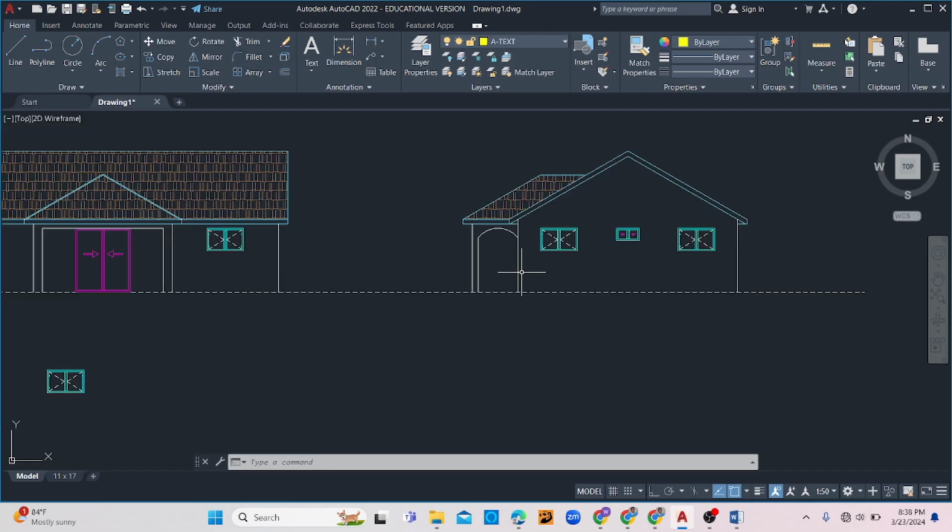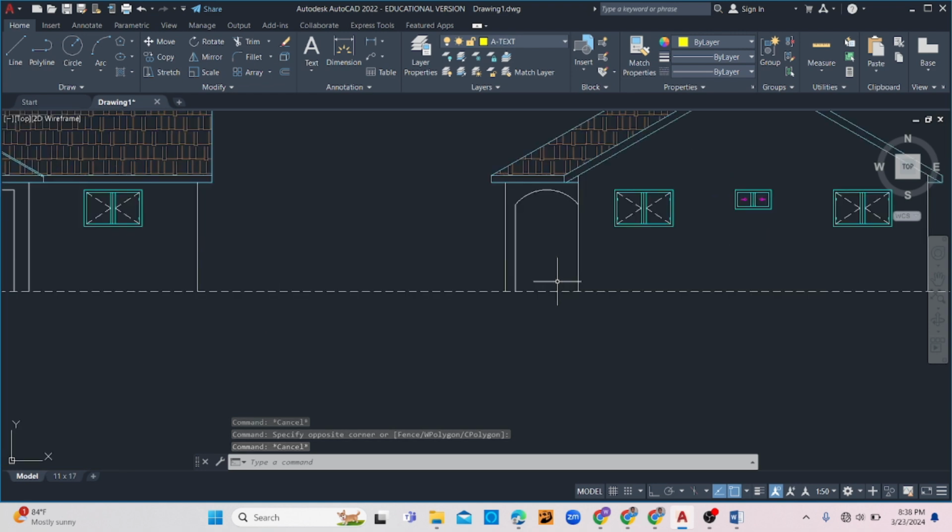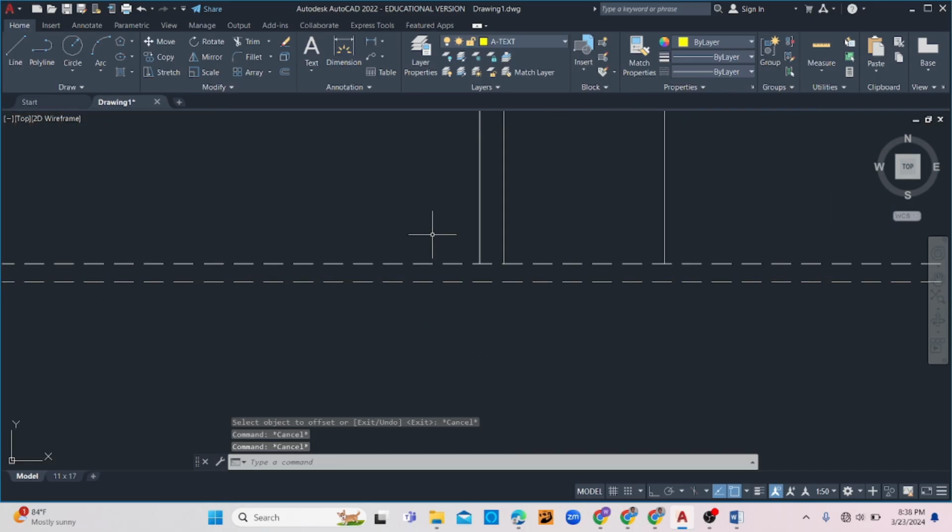So we're going to make our veranda or porch a bit lower than the inside of the building. This line here represents our floor. We don't want rainfall, breeze, blowing some wind, and then the water goes inside the house. So we're going to make it a bit lower. How much lower? We're going to make it about 6 inches, which is about 150 millimeters. So what do we do? We offset this line here down by 150.